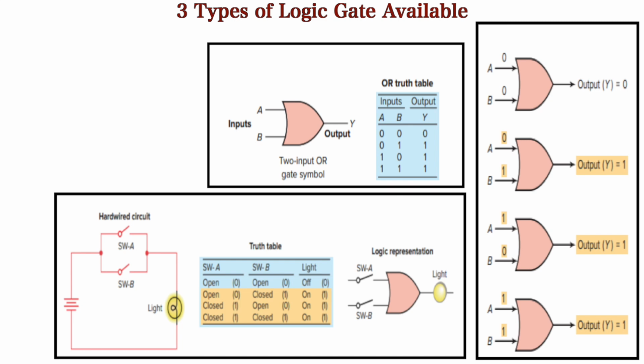You can clearly see all the 4 cases in the logical diagram here: 0 0, 0 1, 1 0 and 1 1. In the OR function we get the 0 output in only one case, when both the inputs are 0. We get the high output, or 1, in all the remaining 3 cases: 0 1, 1 0 and 1 1.